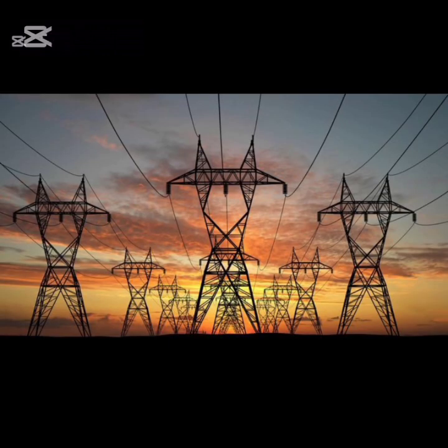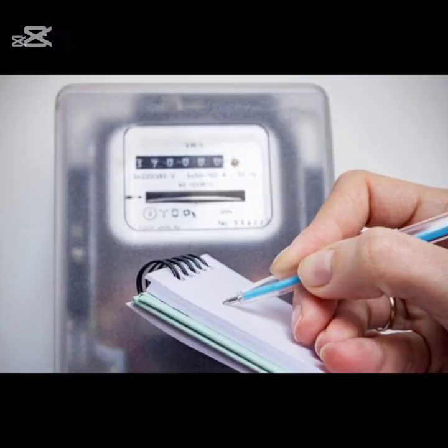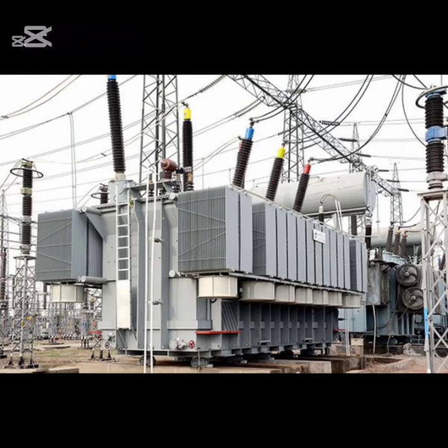2. Poor voltage regulation. As current increases in the power lines due to low power factor, there is a greater voltage drop along the length of the wire before the receiving end. This can result in inefficient delivery of voltage to end users. 3. Higher electricity costs. Many utility companies impose penalties for customers with a low power factor. This results in higher electricity bills, shifting the cost burden to the user.